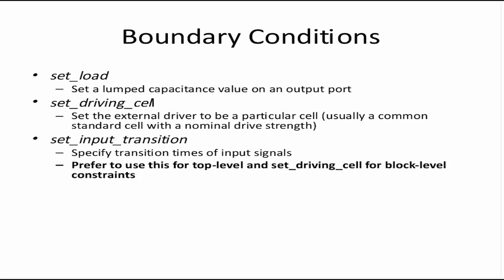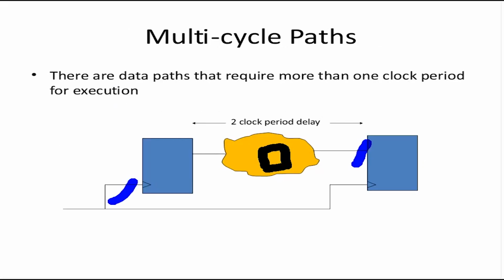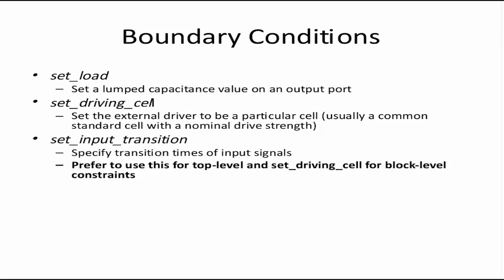The idea of this session is just to introduce you to the concept of multi-cycle path and false path. Again, the boundary conditions the STA tool checks are the same as what Design Compiler does, but please note that post-layout STA has actual net parasitics. The boundary conditions are something you could specify in STA. Again, they are the same commands: set_load, set_driving_cell, set_input_delay, same as what we discussed in unit 2.